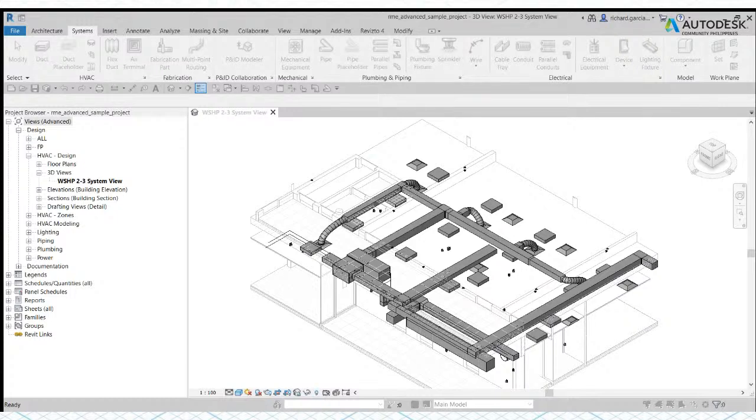Let's say I want to create a shortcut for extend. I need to search it first, so I can type here extend. We have extend here. Let's say trim extend single element. There's no shortcut here, so I'm going to select this one, and then type the shortcut here. That's how you create or customize your shortcut.